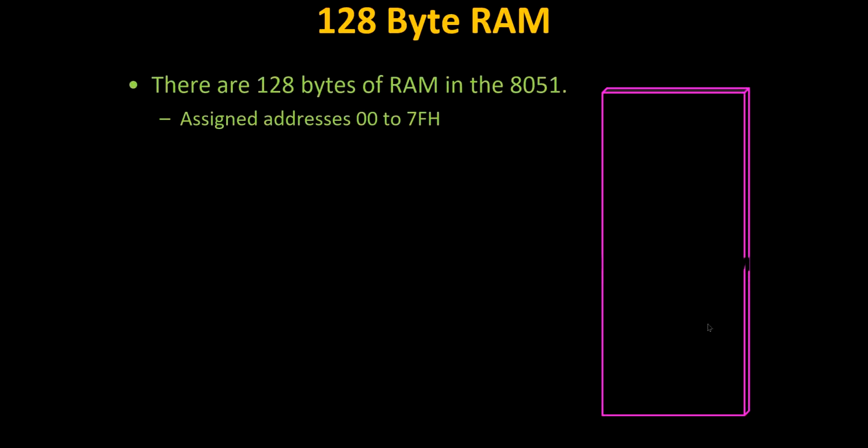Coming to the 128 bytes of internal RAM, all are addressable, from 00 to 7FH, that is totally 128 bytes of RAM in the 8051.